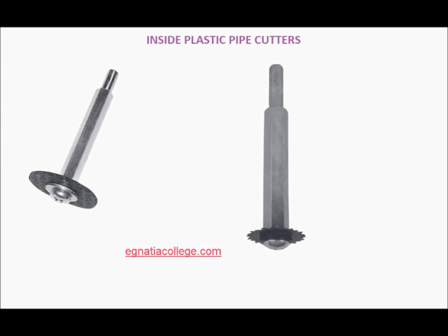Plastic pipe in a difficult location must often be cut with a drill and an inside pipe cutter. For example, if a drainage pipe is installed below a concrete floor, or the piping cannot be accessed from below a work area, the plastic pipe can be cut from the work area with an inside pipe cutting tool.